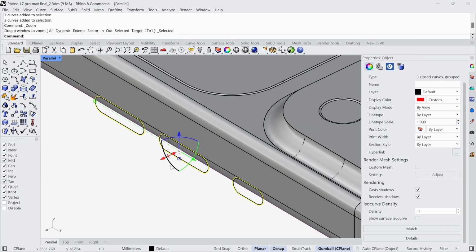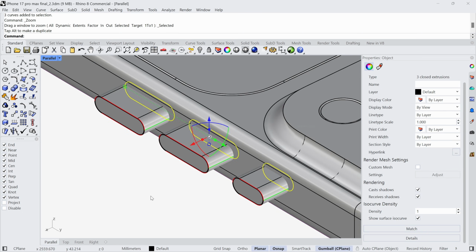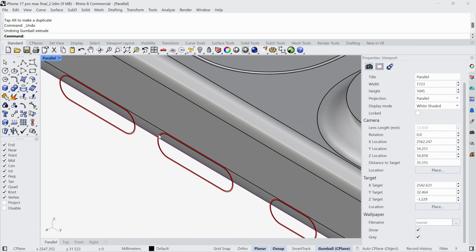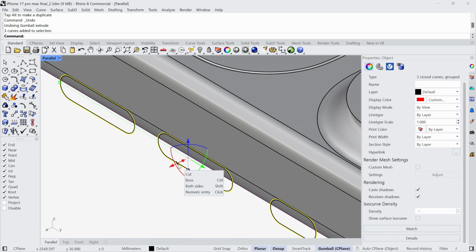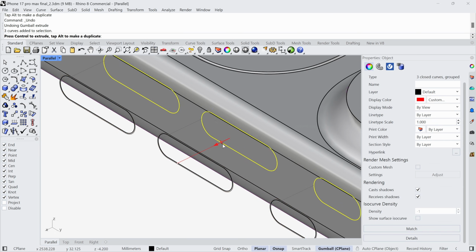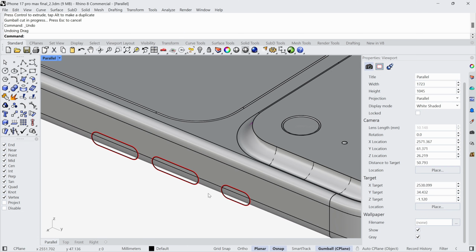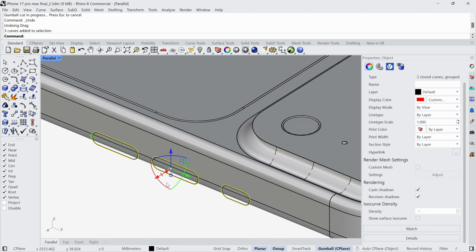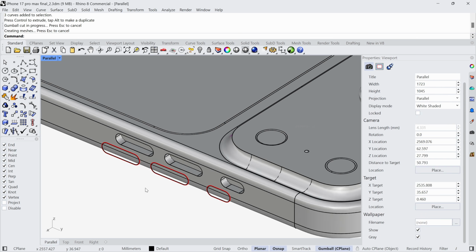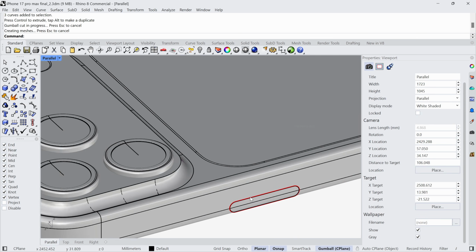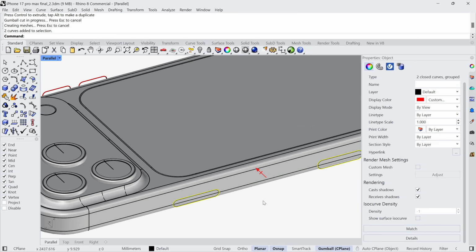First, let's select the red curve, and we can either extrude it and perform Boolean difference, or I can use the handle, the line handle, to create the cutout shape. So let's see how we can cut it. Let's select the red curve and move it by -5 plus -2, so -7 units. We can click here and write -7. Similarly on the other side, select the red curves, 7 units in this case.